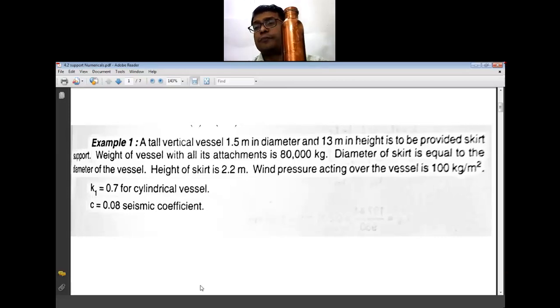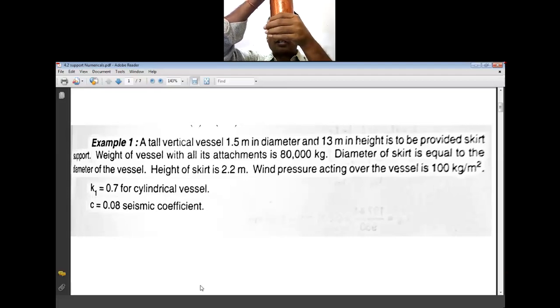So FC minimum into A, that is the surface area of the anchor plate upon the number of bolts. So stresses on the bolt is equal to load on the bolt upon the area that is to be calculated, and the area for the anchor bolt is calculated as 1 upon NFB into bracket 4M upon DB minus W. So this is the general overview related to the designing. Now let us come to the numerical associated with this.